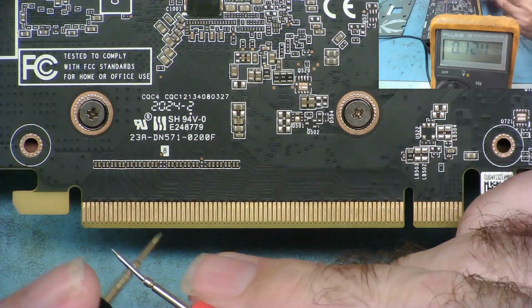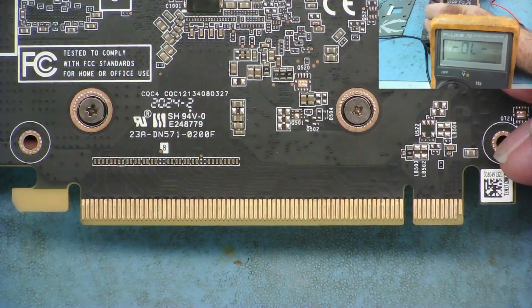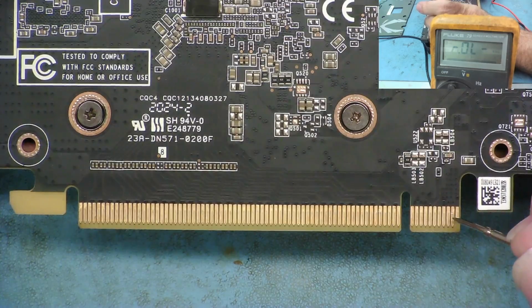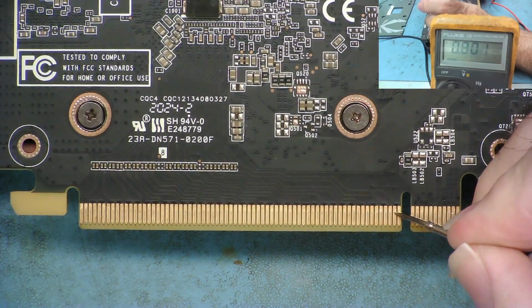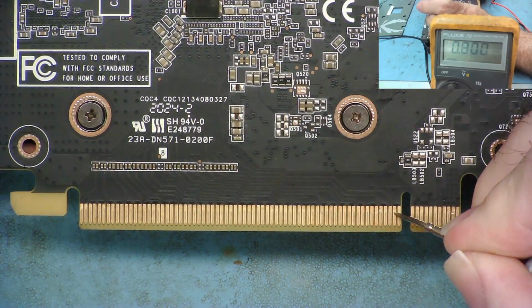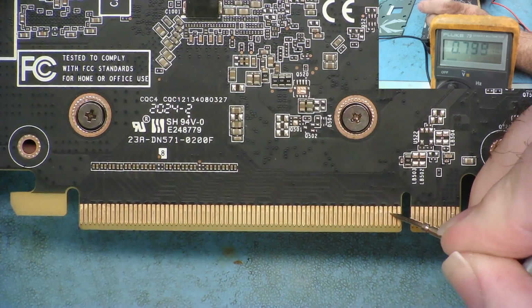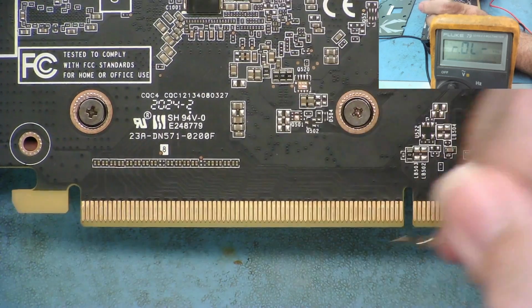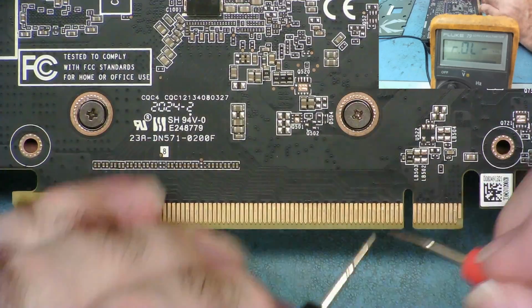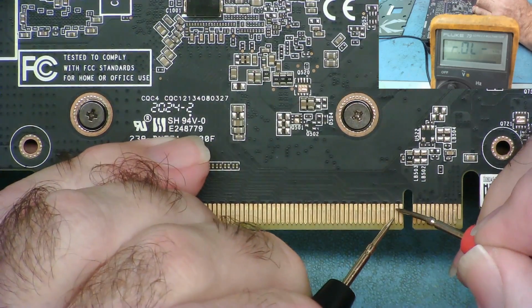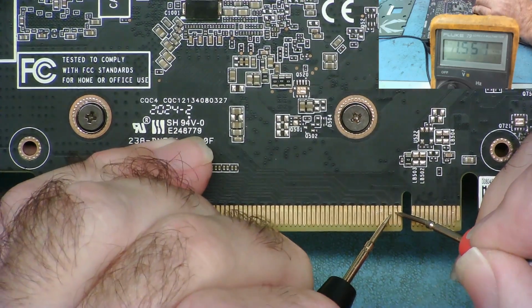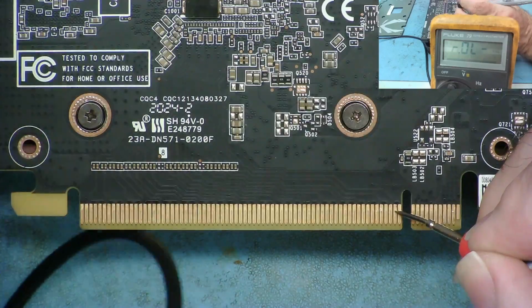I'll just check the meter. Yeah, it's good. I'll go to ground of the black lead, and let's have a look to see what's on pins 2 and 3. So here's pin 2, and that's reading 800 steady, and pin 3, 800 steady. Again, I can't say exactly what they should read, but they should read the same as each other, and they shouldn't be shorted to each other, which they're not.